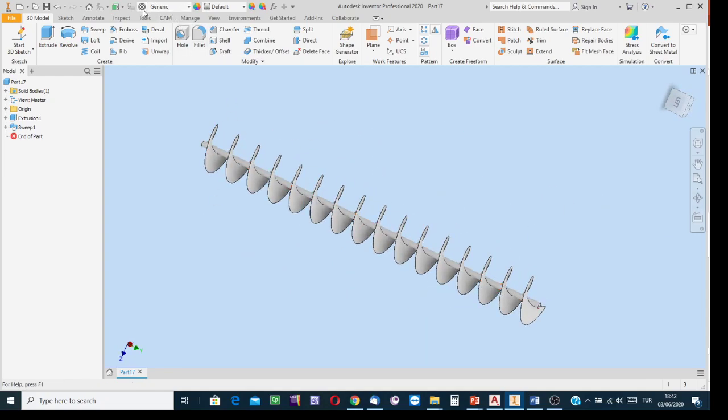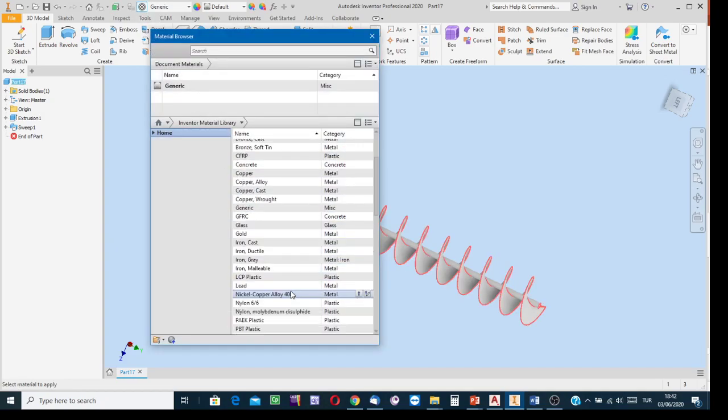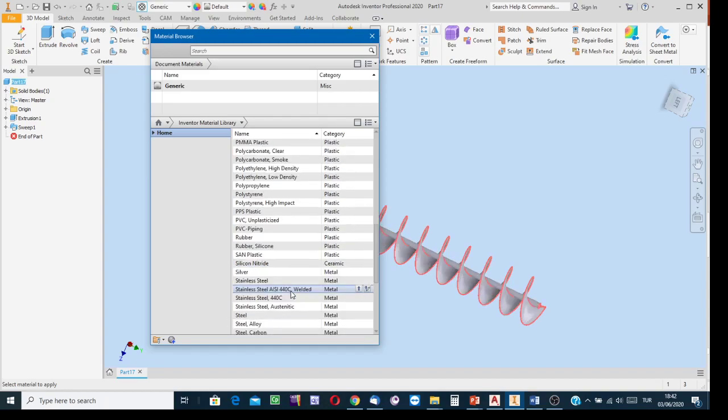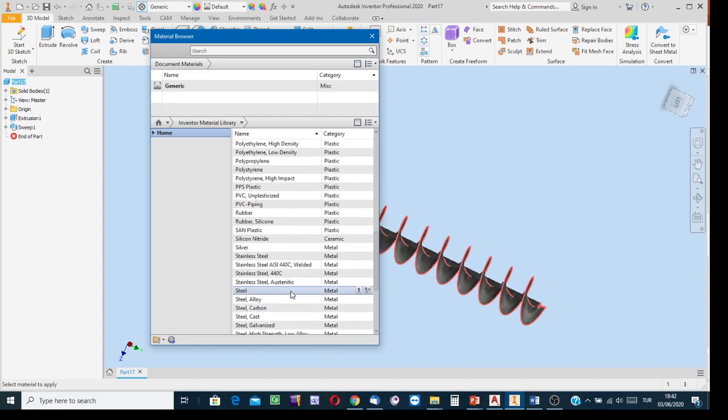Say it is made of stainless steel. Okay, or depending on the type of the material it is to convey, elevate or pump, select a suitable material for the rotor. It shouldn't chemically react with the other material, be it water or any kind of liquid, or say that the material consists of little granular particles.